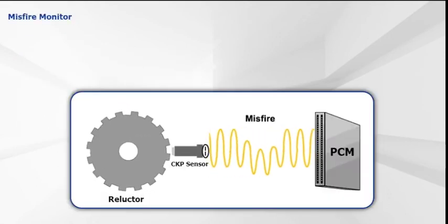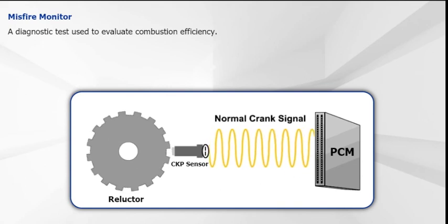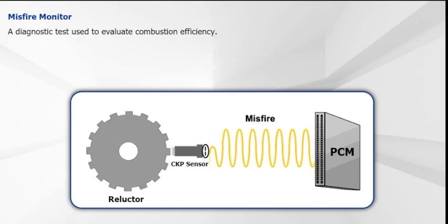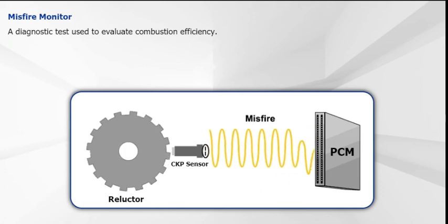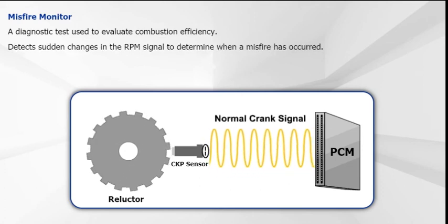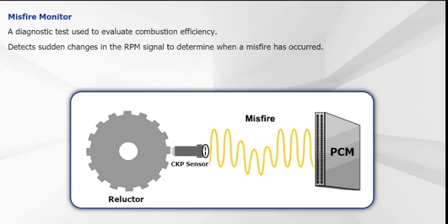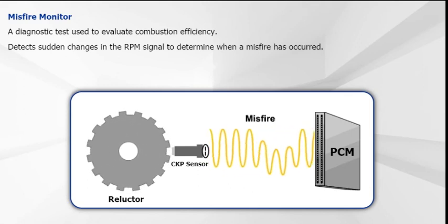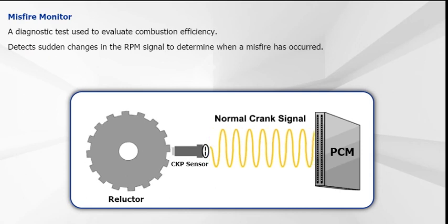Readiness status is one of the required test functions for a scan tool. In this mode, all of the system monitors will be displayed along with corresponding messages indicating if the tests have been run. Keep in mind that readiness status does not indicate whether a given monitor has passed or failed, only if the PCM has executed the test.